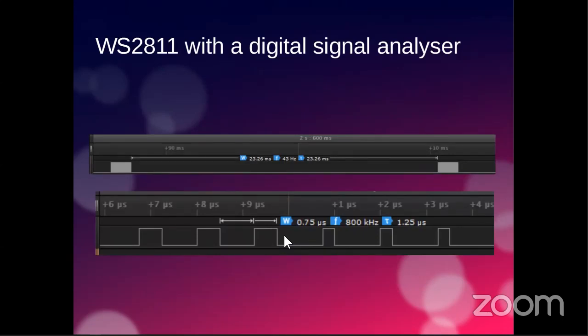And so Dave runs his signals right at the top end of that error factor to provide the best experience and the most compatibility. You can see also that the controller is sending this blob of data. There's a whole bunch of pixels being sent here. And then there's this long quiet period before it sends the next frame. Now I was only running my 38 pixels or so, so this is actually quite a large amount of downtime. So that's what it looks like digitally.